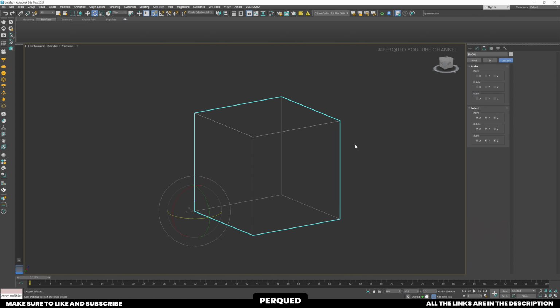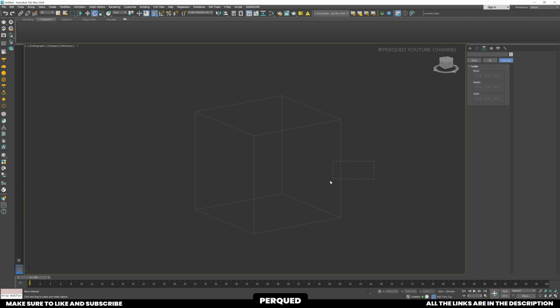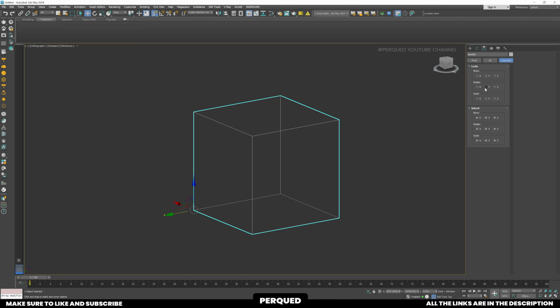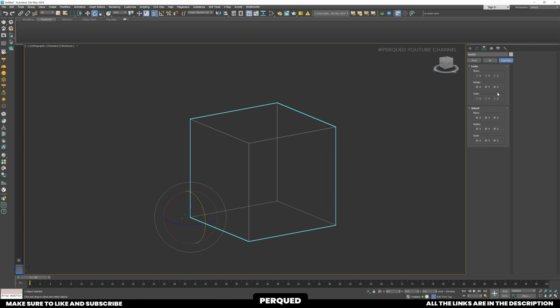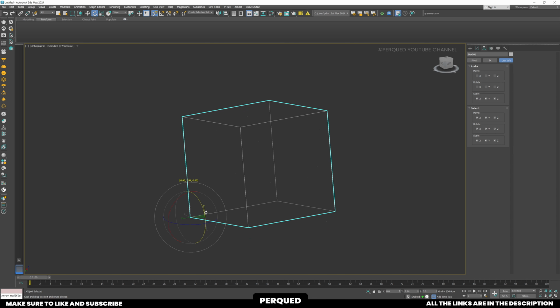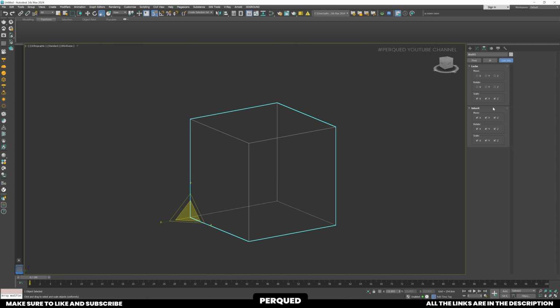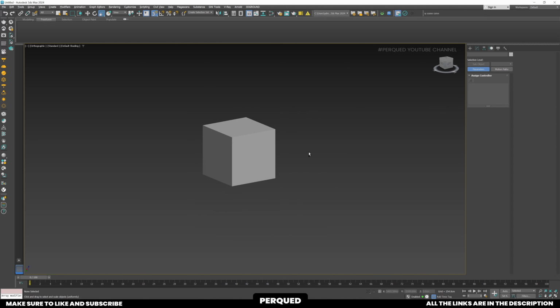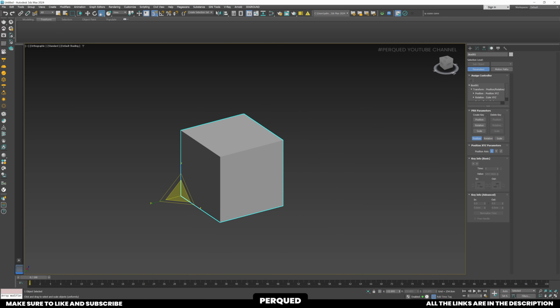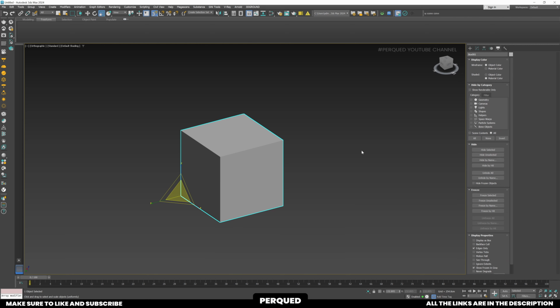For locking certain transformations, select the object, go to the hierarchy tab, link info, and lock X, Y, or Z of move, rotation, or scale of the object. I haven't ever used the motion and display tabs in the last 5 years, so we can skip that. If I ever find good use of these tabs, then I'll definitely look into it. For now, let's skip it.